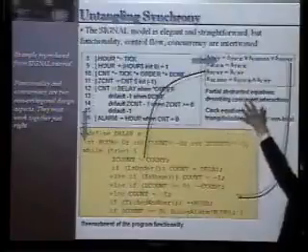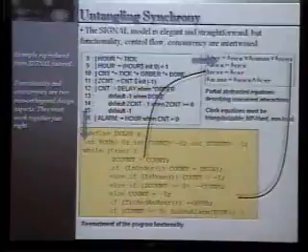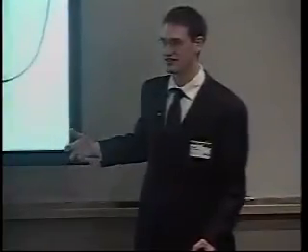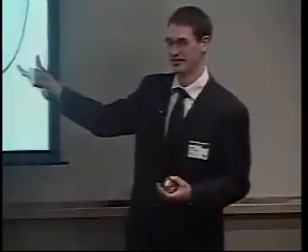But this isn't so easy to do because causality analysis is a global property. The way you calculate it is you take all of these equations, you try to find a triangularizable version of these equations that takes into account all of the causality constraints. And if you find that, then you're good. You found a solution to the system. If you don't find that, then something's wrong. But what's wrong, it can't tell you because the process fails because it can't take this whole set of equations and find a reasonable interpretation for them. So you can't point to any one equation and say, that's the bad one.